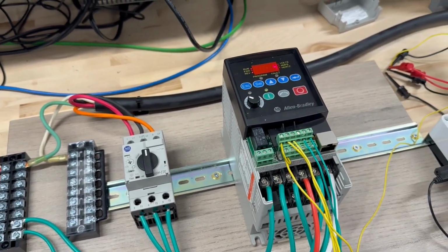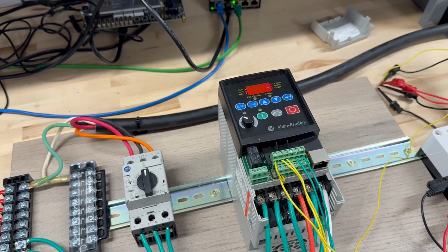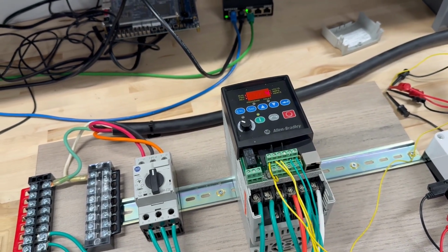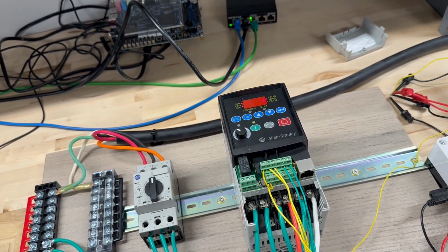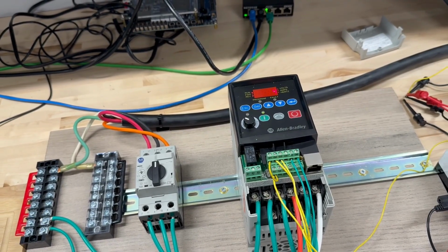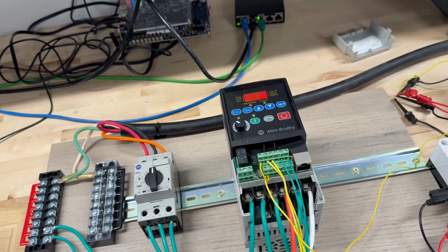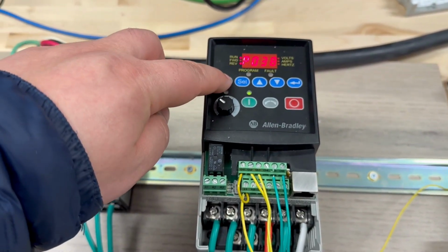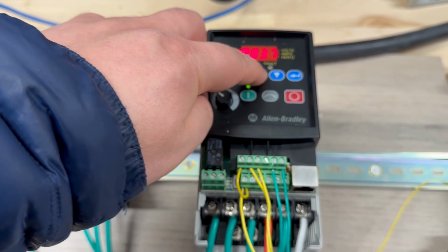So these are the things that we need to check before going to the main parameters for preset frequency with terminals 5 and 6. For preset terminals, for sure we should set A051 and A052 to 4, which is preset frequency. Let me double check and make sure we actually have it.